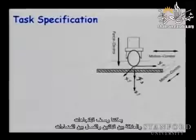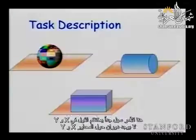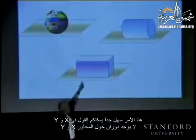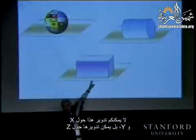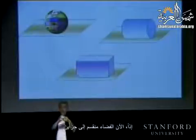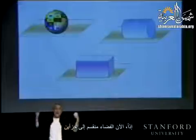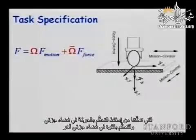And we can now describe the directions and the relationship between the two and separate the spaces. In here, it's very easy. You can say in x and y, there is no rotation about axes x and y. You cannot rotate about x and y. You can rotate about z. But in the z direction, you cannot move, but you can move in x and y. So now the space is split into two parts. And to split the space, we go to a description of the space, and we split it through these omega matrices that allow us to project the motion control in some subspace and the force control in another subspace.